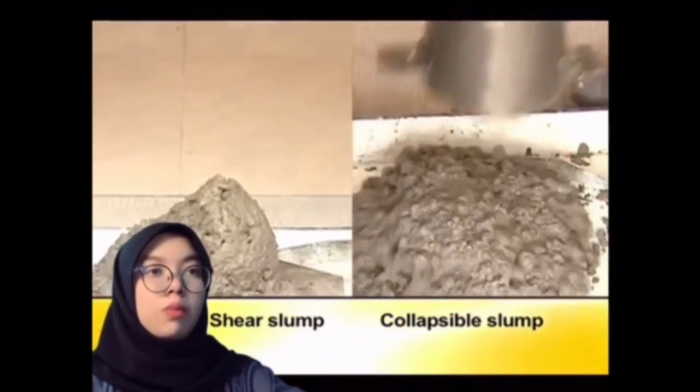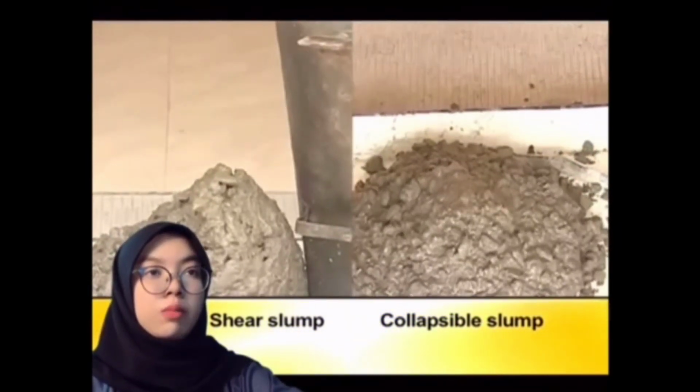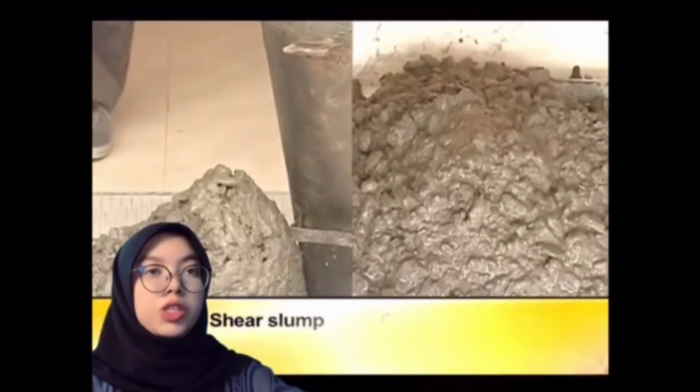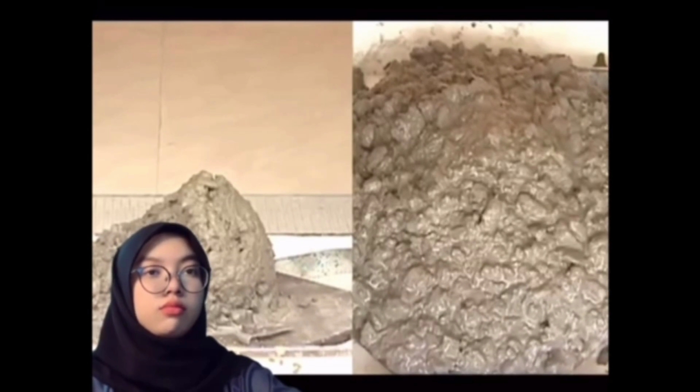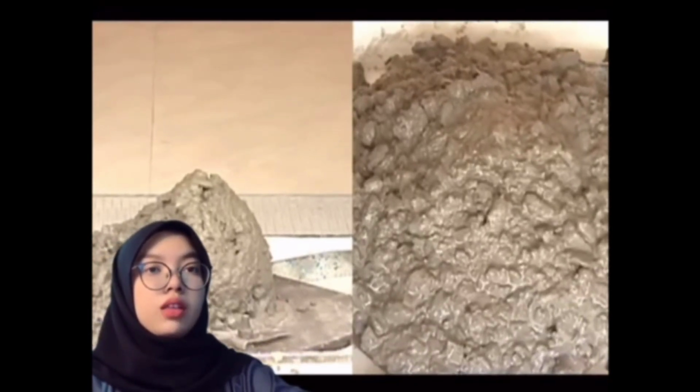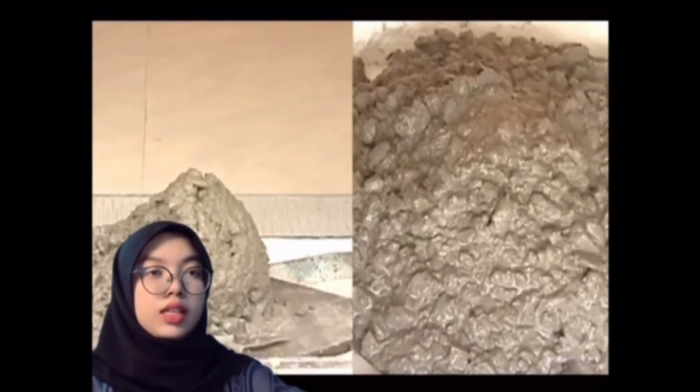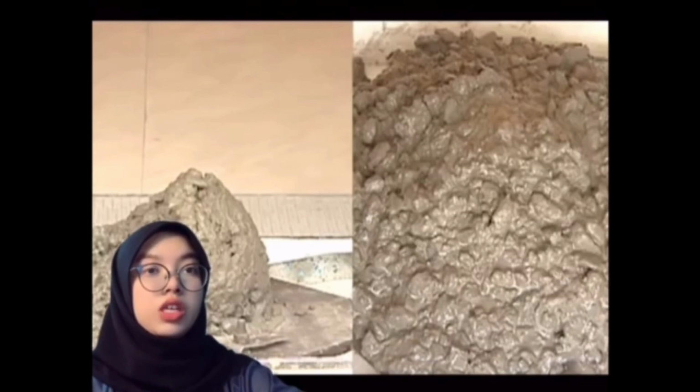In case of slump results beyond the specified limits, the mix proportion needs to be adjusted, especially the water content. The slump can be varied by changing the proportion, size, and combination of various sizes of the aggregates.